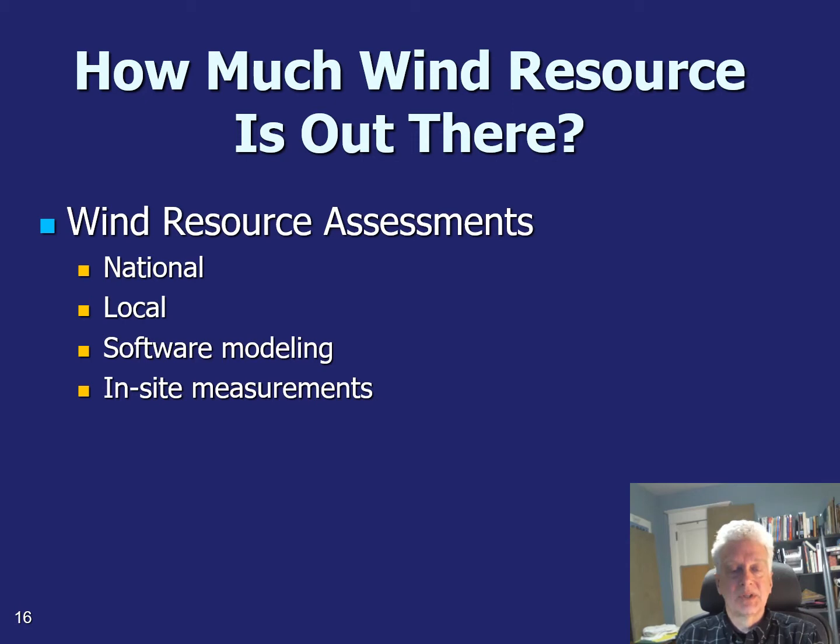You can approach this with aggregating lots and lots of existing wind measurements, but typically you do it with atmospheric airflow models. So you use software, and when you come to an individual site, then you can look at putting in instruments dedicated specifically for the purpose of getting really accurate statistics about how often the wind is blowing, how strong it is. And generally that'll be a 1 to 2 year study.